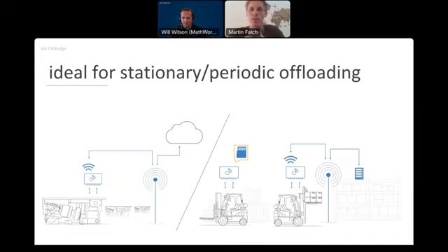For example, if you have a stationary asset, it could be in a production environment or energy environment, you may want to connect the CANedge 2 and then have it continuously have access to Wi-Fi and thus the server. And your experience here will be that whenever a new log file is created, it is automatically offloaded to the cloud. And once successfully offloaded, it is deleted from the SD card. So you can imagine having many of these in the field, and they will continuously upload the data.